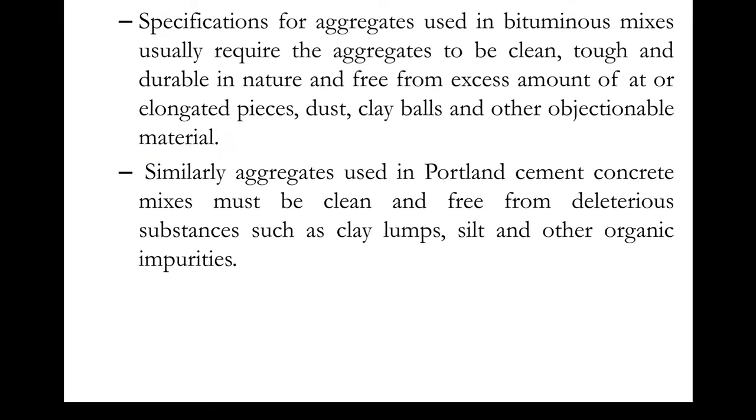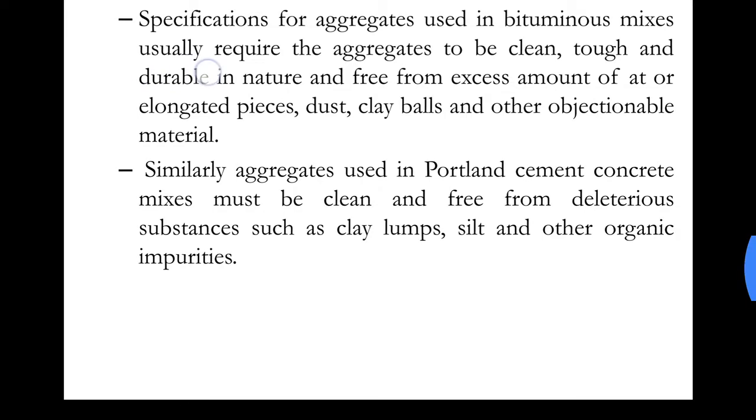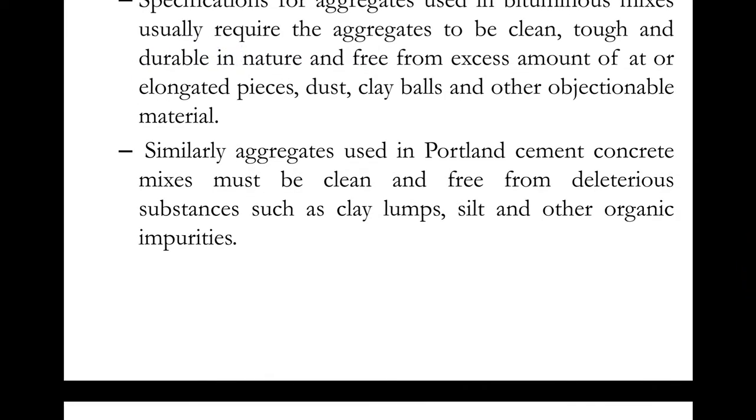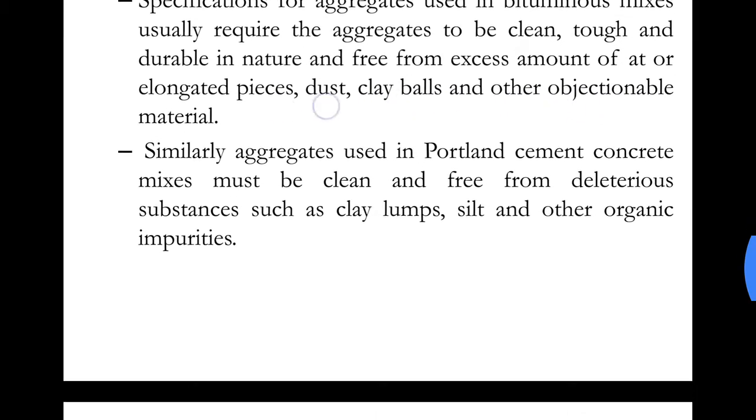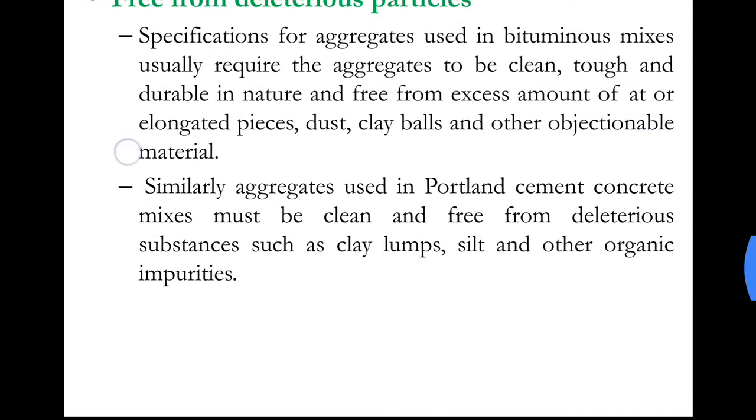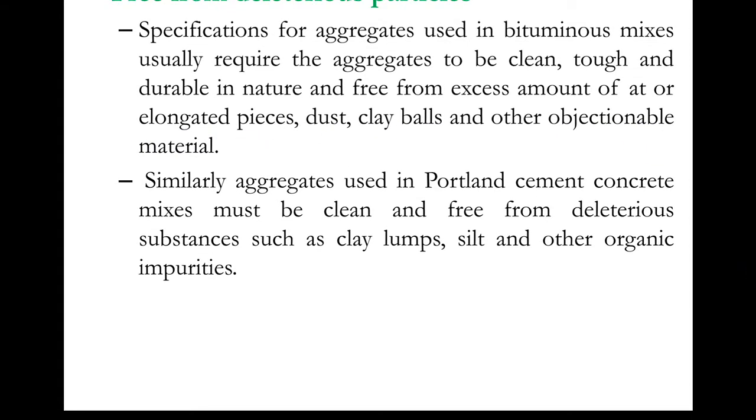So our aggregate should be clean, tough and durable, and it should be free from materials like dust, clay balls or other objectionable materials like grass or wood, or plastic in some cases.